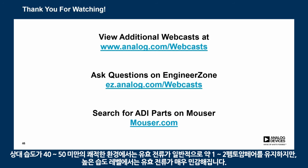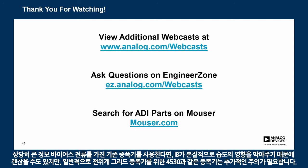But the effective current becomes really sensitive at high humidity levels. If you use legacy amplifiers that have considerably larger input bias current, it might be okay because IB would essentially mask the humidity effect. But for amplifiers like the 4530, for electrometer grade amplifiers in general, extra caution has to be taken.